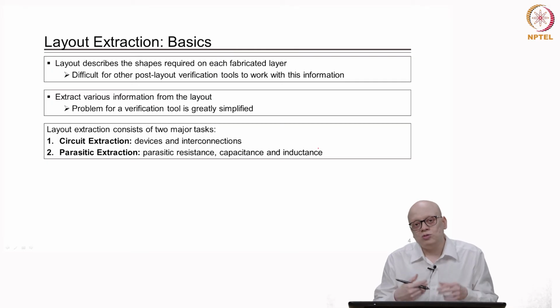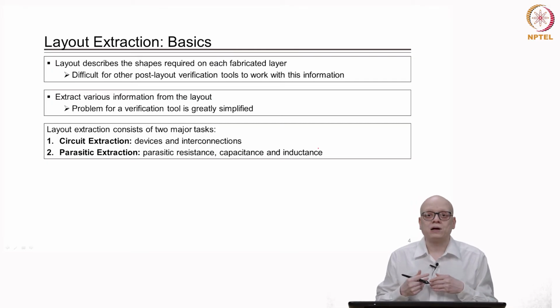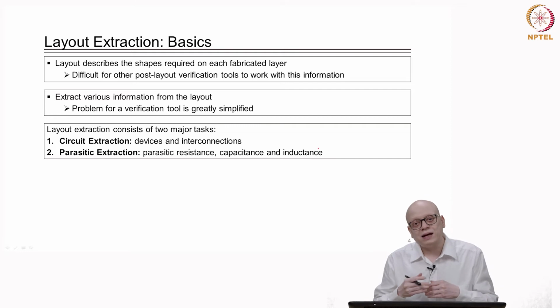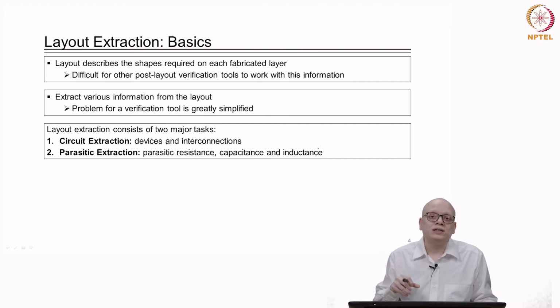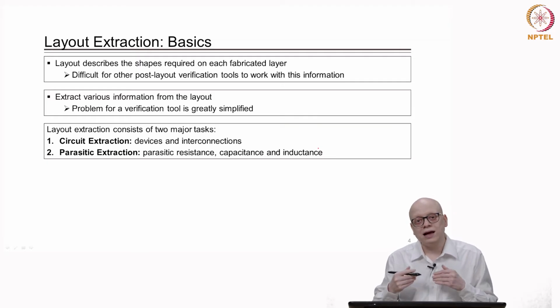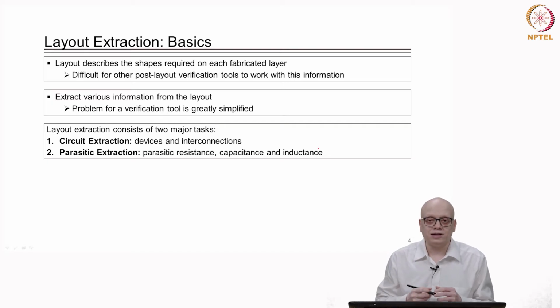We don't intend to create those capacitors, but those parasitic capacitors exist in the layout, and that information also needs to be extracted by the tool, so that, say, the signal integrity tool can comprehend how much the capacitance is between two lines, and based on that it can check whether signal integrity issues are there in our layout and whether we need to fix them.